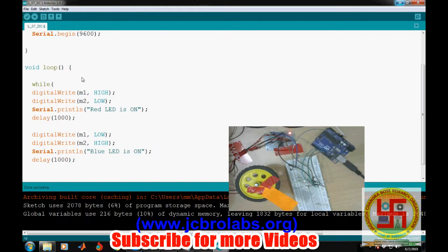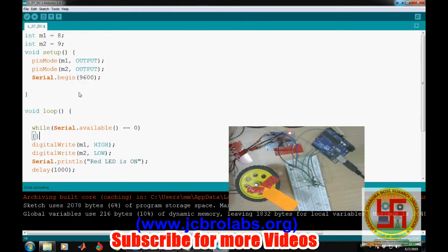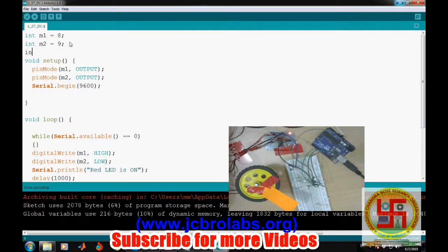So first of all, we will be checking whether data is available to read or not. Serial.available. If the data is not available, then this Serial.available function will return 0 and it will be stuck in the while loop only. And as soon as something is available to read, it will come out of the while loop and we will read the data in another variable, let's say a, or let's say i. We'll read that data into i.